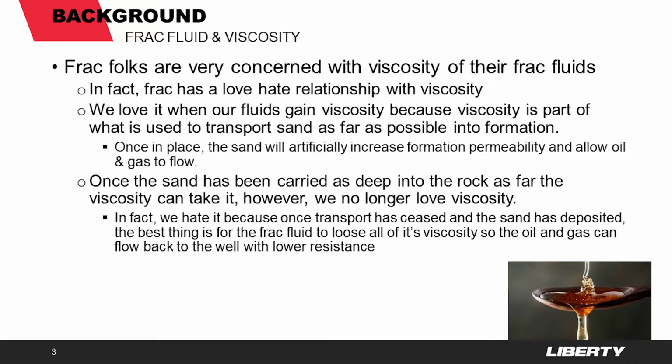Once in place, the sand will artificially increase formation permeability and allow oil and gas to flow. Once the sand has been carried as deep into the rock as far as the viscosity can take it, however, we no longer want viscosity and we no longer love it. In fact, we hate it because once transport has ceased and the sand has deposited, the best thing for the frac fluid is to lose all of its viscosity so that the oil and gas can flow back to the well with lower resistance. So how do frac folks like to measure viscosity?